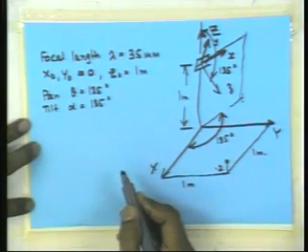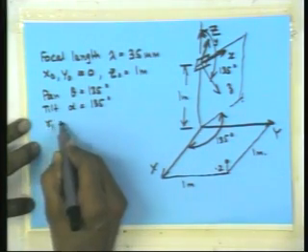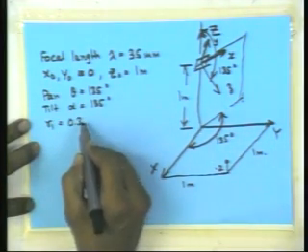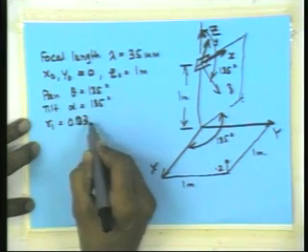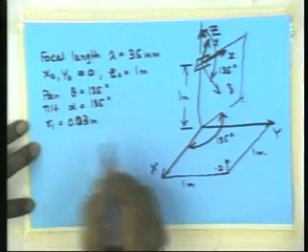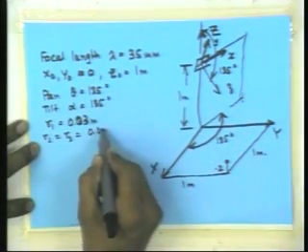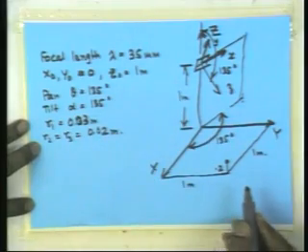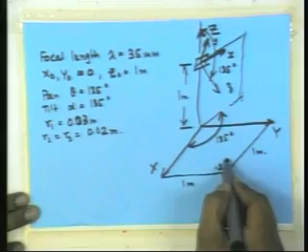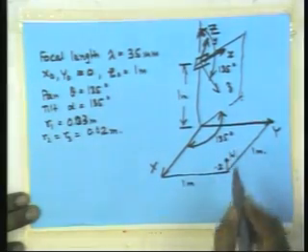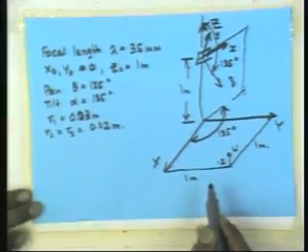All right. Now, we also need to know R1, R2 and R3. So, let us say R1 is equal to 0.03 meters, and R2 is equal to R3 is equal to 0.002 meters. So, now I have all the information. I will be able to compute what this point W looks like in the camera coordinates, which will be somewhere on this plane, right.